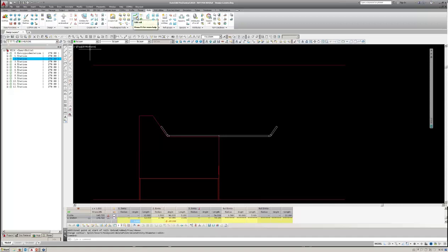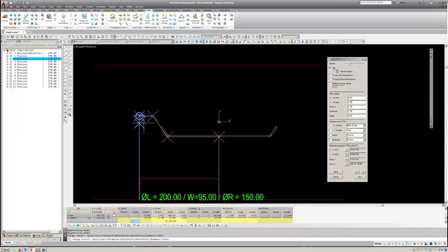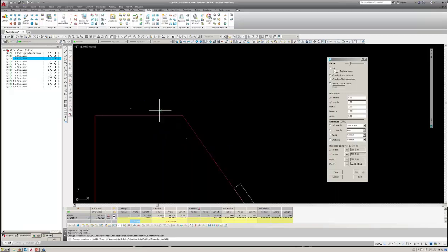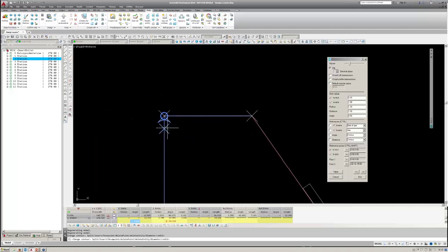Now if I just go into edit the roll, we can see here the 5 markers I was talking about earlier. Here I'm going to add a radius to the end, and this is one tool I really like. I pick this area, left mouse click, and you can see now by dragging the cursor the radius is shown dynamically. However, if I hold down Control and Shift, you can see my radius now is moving by the definition there in the grid values in 1mm increments. So that's Control and Shift to make that happen.